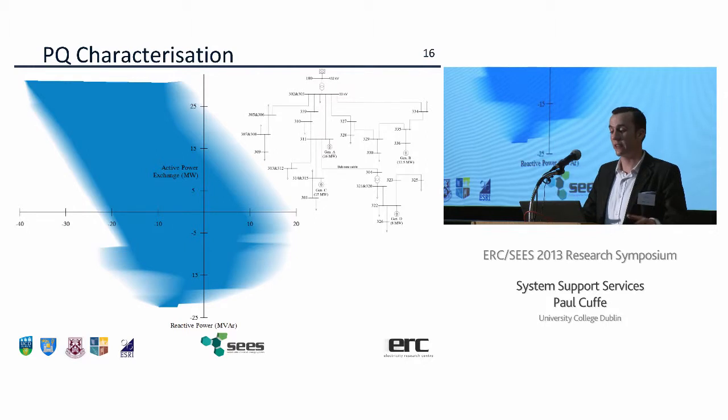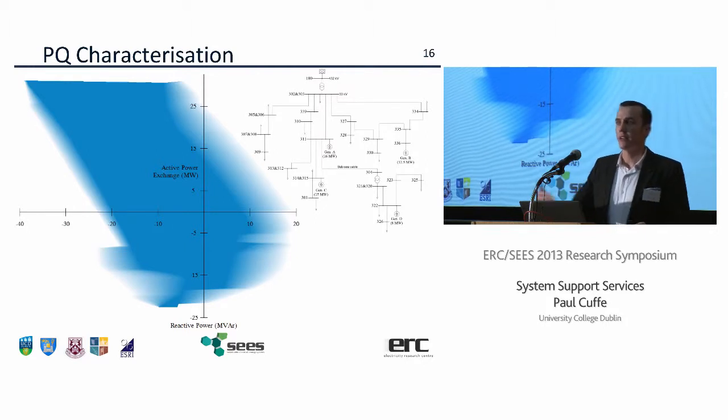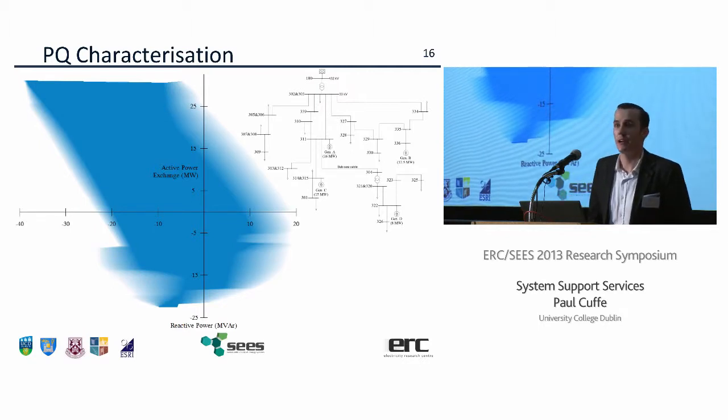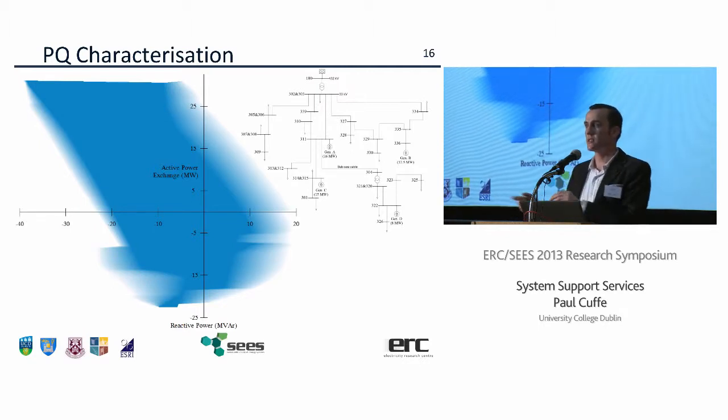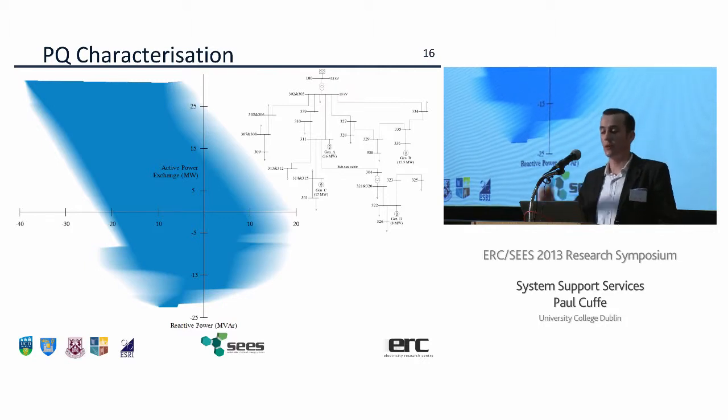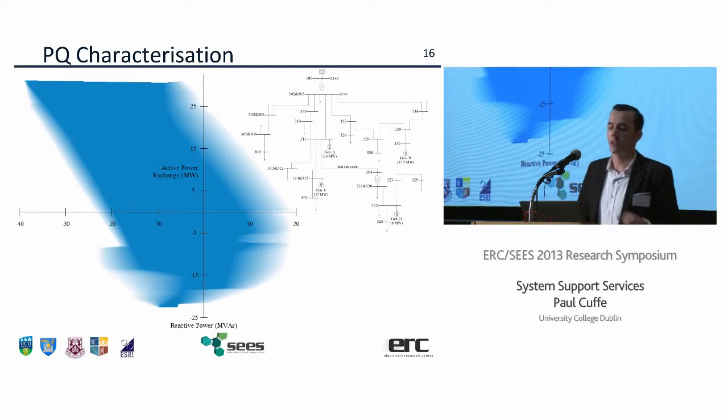And it turns out that the reactive power you get depends on the active power flow. This is a key thing at distribution level. The two flows are kind of entangled. In the initial diagram they showed for the transmission system, they're two separate things going on. For distribution systems, they affect each other. So as the active power output increases from this network, the wind goes up, the whole network starts to export active power. That cuts into how much reactive power you can provide.